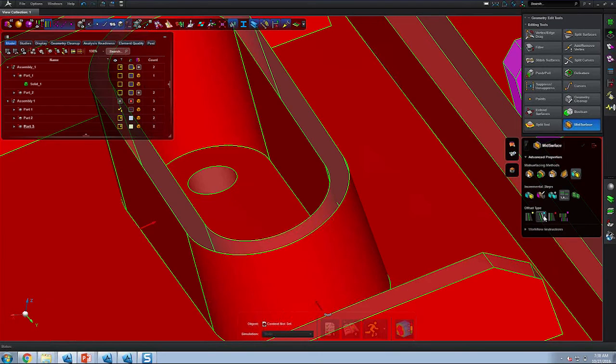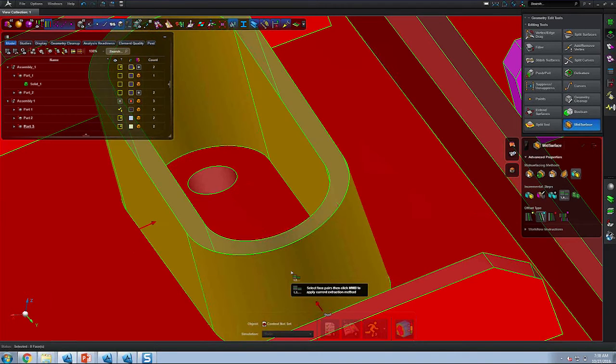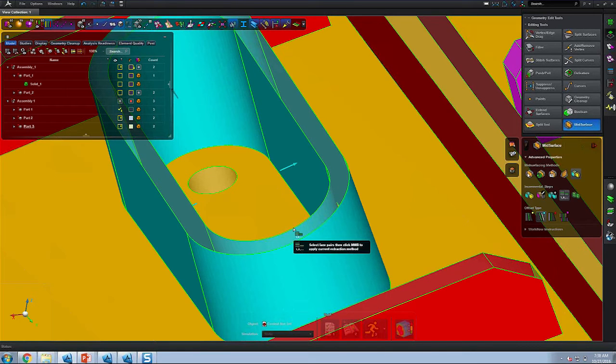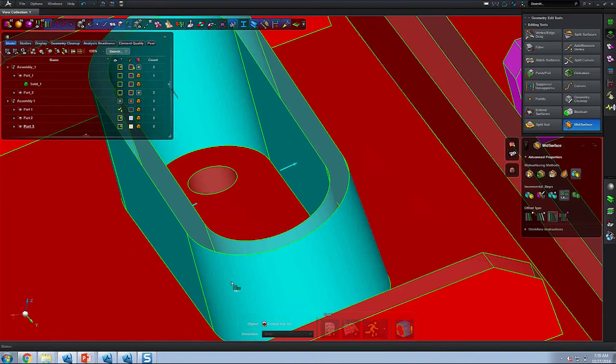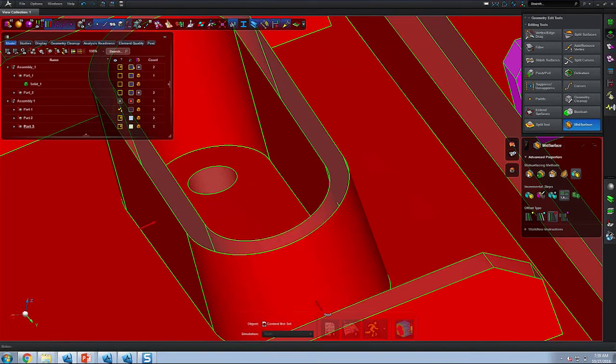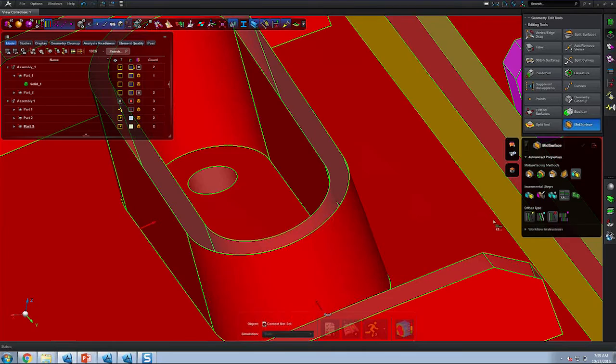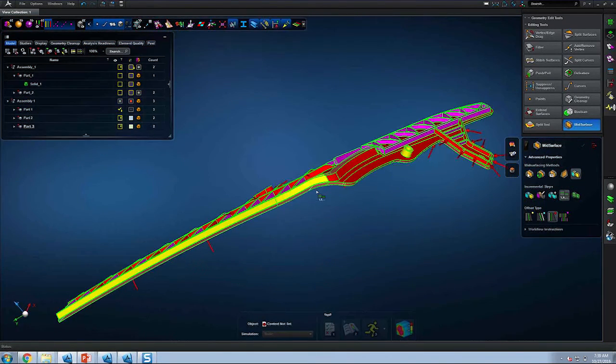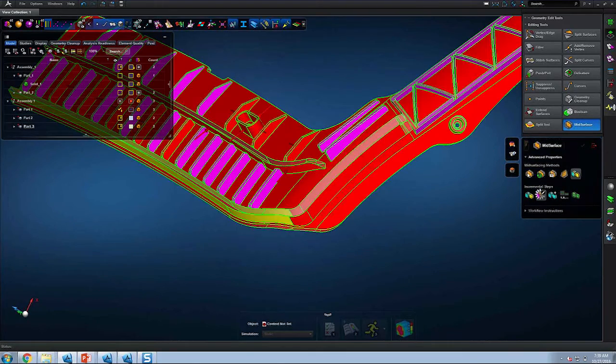What you can also do is select a different offset type. And so then when it extracts the mid-surface geometry, it will first take the faces of the inner region of this piece and then project those inward to create your mid-surface geometry. So that's what the offset type means. Here previously it was using what looked like the yellow offset type, and I've corrected this to be the red offset type. So in a moment you'll find the benefit of doing that.